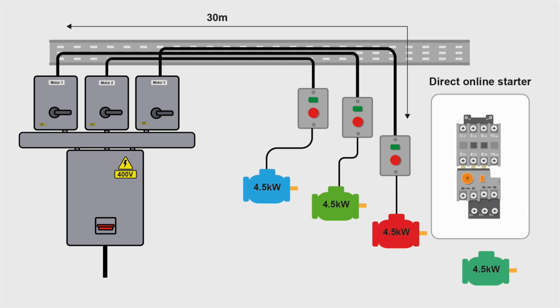So from this switch fuse here to the 3-phase induction motor, a run of 30 meters. In this certain set of circumstances, 1.5mm cable is acceptable. Don't forget that's 3 times 1.5mm square cable. It's a 3-phase motor. There's one of the benefits of 3-phase. You get more power and you don't need such a large cable.